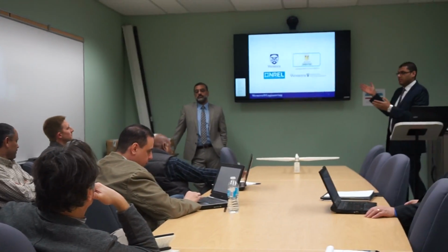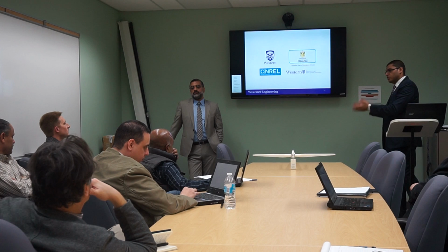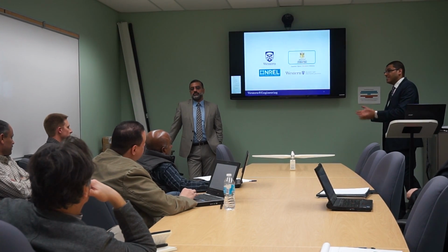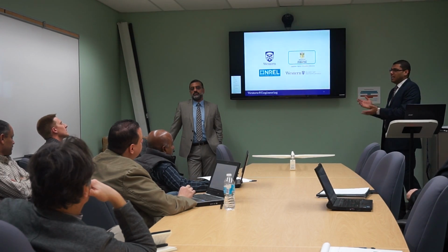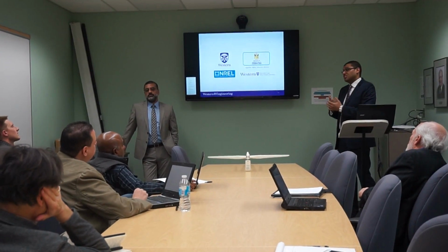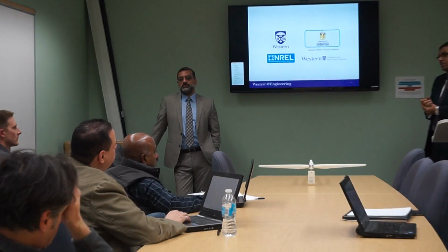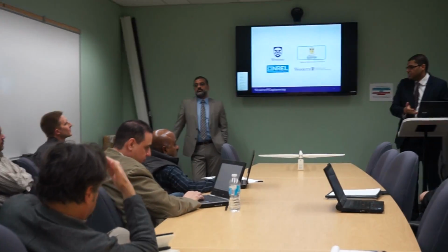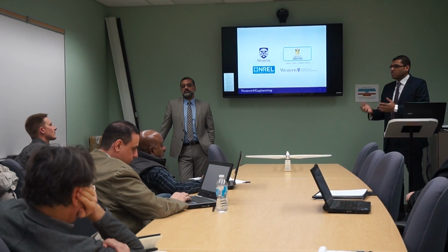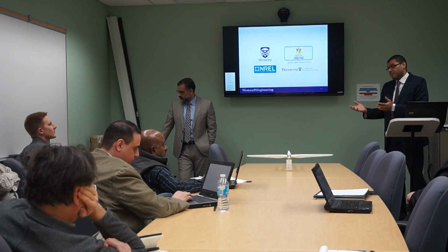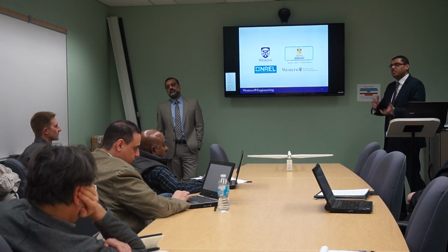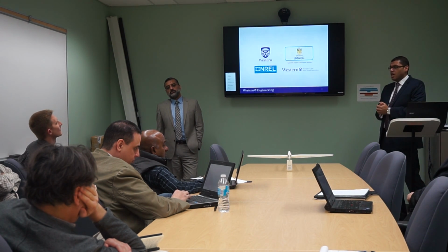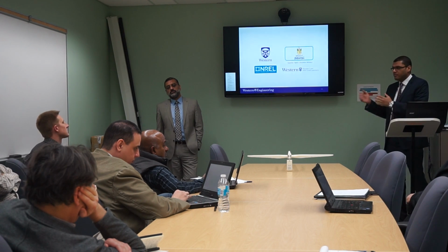Yeah, as you can see, the lateral and vertical displacement will be less than the 6 meter diameter. The main concept here, as we said in the introduction, is experience in construction. So in the North Sea, they are just depending on gravity base because they have experience in gravity base. If you just have experience in monopile and don't have experience in this hybrid foundation system, it will be a little bit hard to have all the equipment for it. So this will be the major obstacle in this hybrid foundation system.